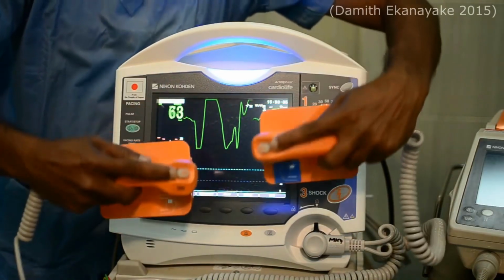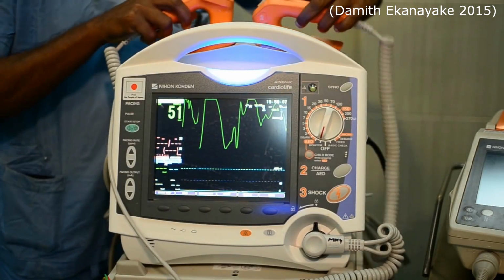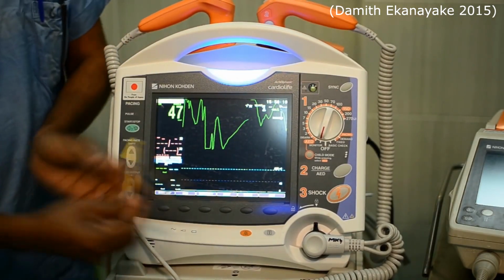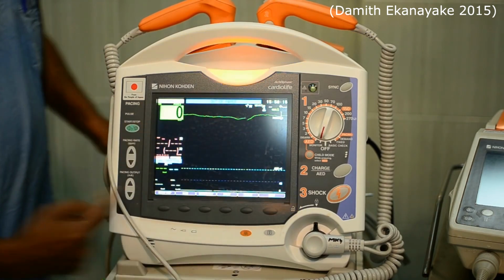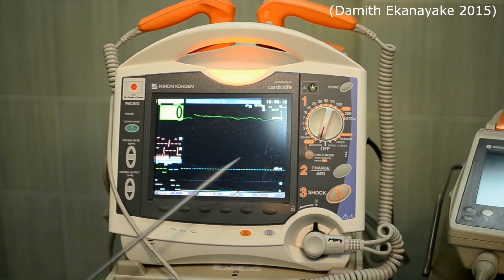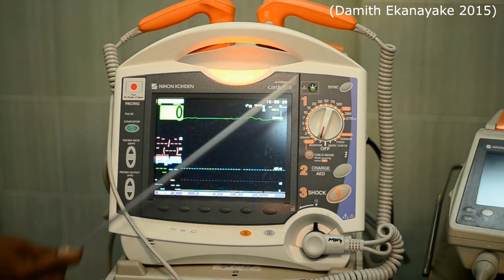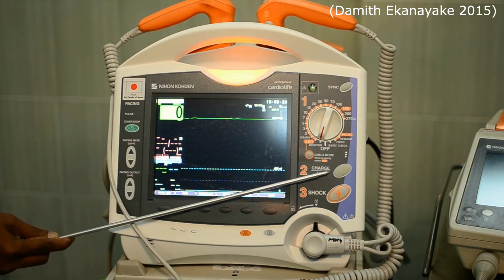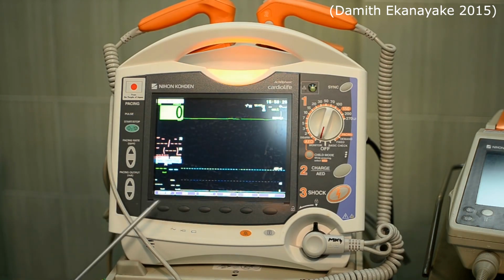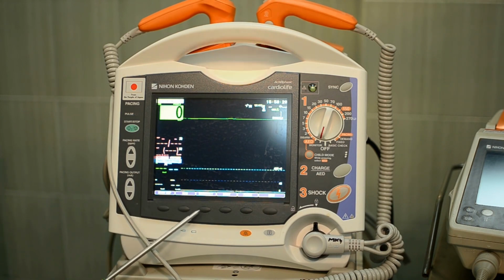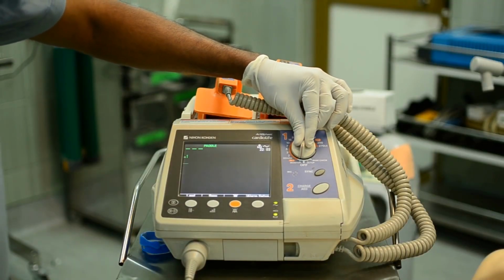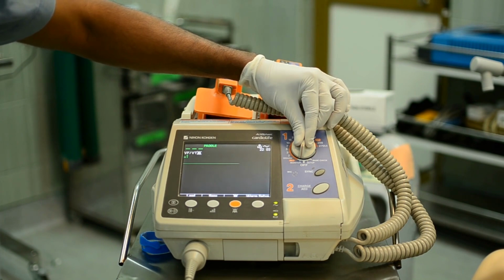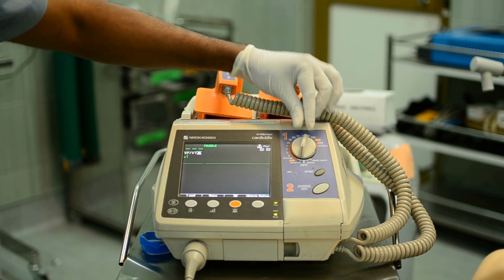A crucial electrical component in defibrillators is a device called a capacitor. So what is a defibrillator? Defibrillators are devices that restore a normal heartbeat by sending an electric pulse or shock to the heart. Defibrillators need a source of power or current to work. Therefore, defibrillators are easy to transport and they often get their power from batteries. Batteries only produce a continuous low flow of current. Therefore, the defibrillator somehow has to use the continuous flow from the battery to provide a brief high flow of current needed for defibrillation. Hence, a capacitor is used as it stores charges.